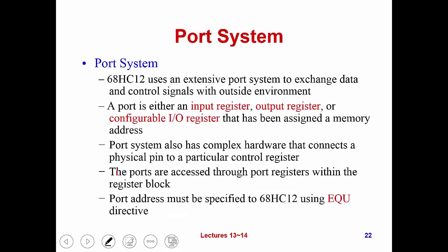Now let's talk a little bit more about the port systems. As I just mentioned, the MC9S12 has extensive port systems designed to exchange data and control signals with external devices. I mentioned it has a larger number of ports in comparison to the 68HC11, which has much fewer port systems.